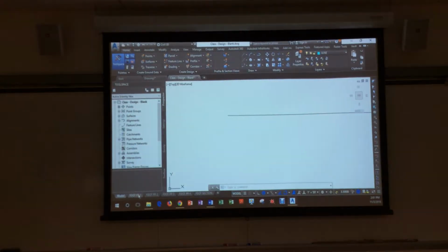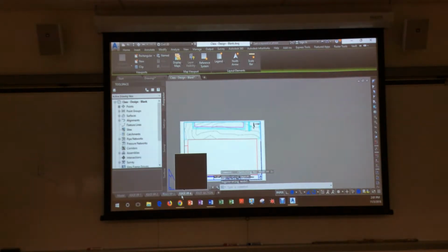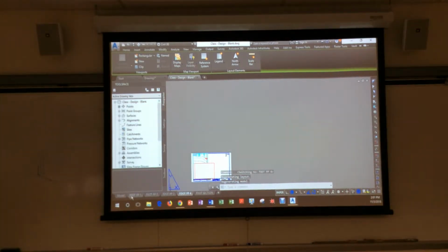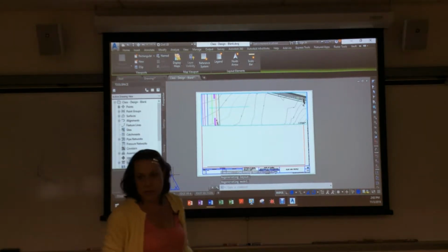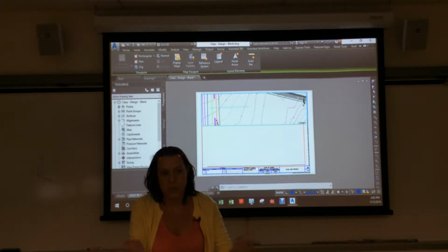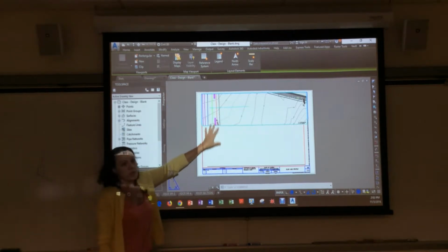And if you take a look at the PP1, PP2, PP3, plan and profile, plan at the top, profile at the bottom, I got them kind of set up so it should fall in place for you so you're not having to worry about viewports as much. I'm trying to be helpful to you in that. So when you use this template, you have the views already set up.